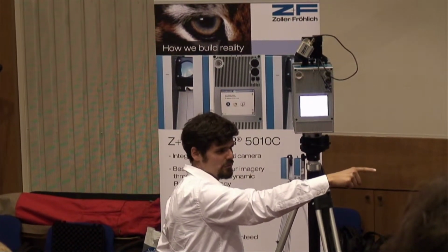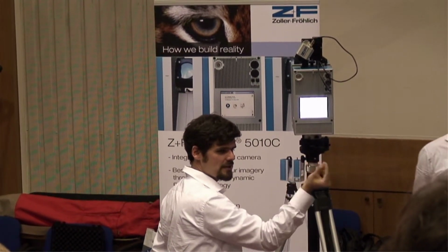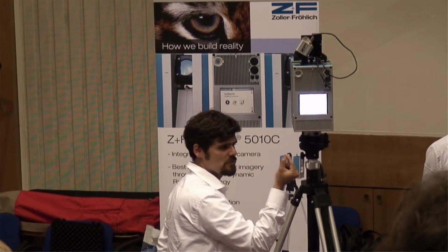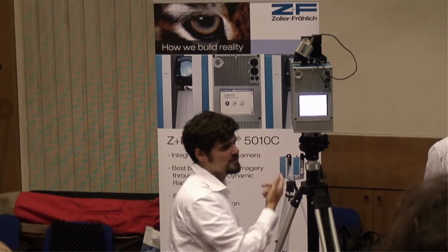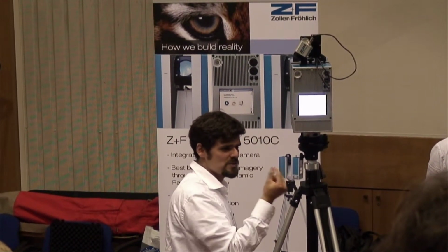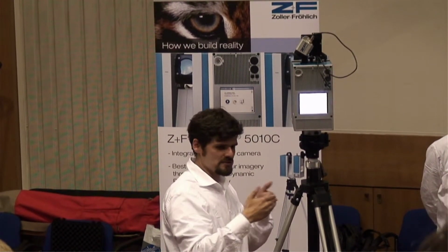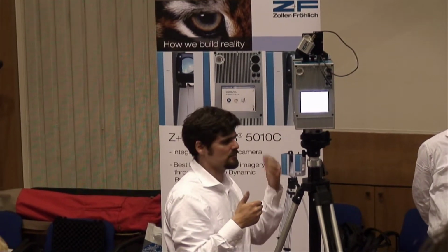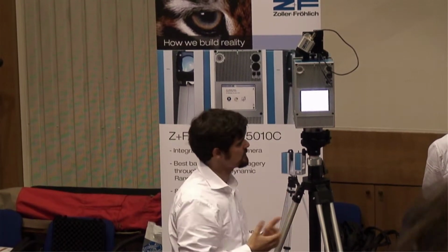It can measure that point thousands of times in that 1 second, and then just average it to the one measurement. So it's got quite a lot of time to measure one single point. If you've got an instrument which measures 1 million points per second, it's got much less time for the same point. So the noise in your measurement increases or decreases with the time it takes to scan.